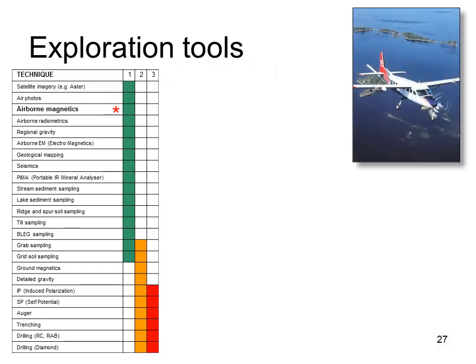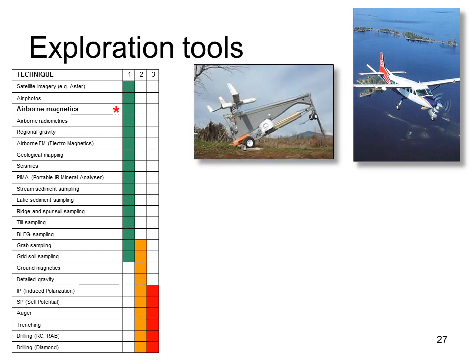Down the list, airborne magnetic surveys provide a very quick and relatively cheap method of collecting data when measured on a per square kilometer basis. Recently, there's been increasing use of ultralight aircraft and pilotless drones with miniaturized equipment as instrument platforms. These surveys can detect magnetic rocks through cover. The method is great for exploration for buried magnetic ore bodies and host rocks.